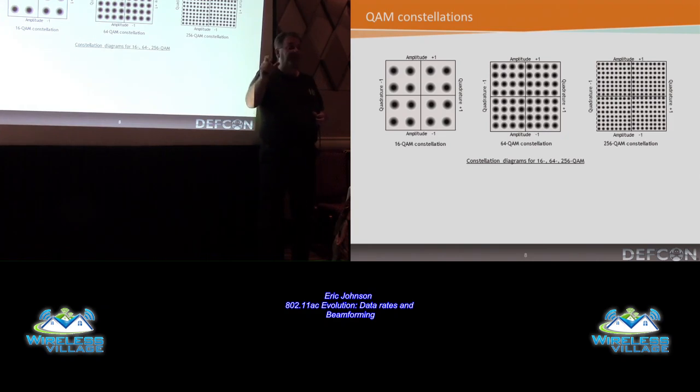Now, there's some fancy mathematical tricks in the transmitter to scramble the bits and to randomize them to make sure that you don't get too many 1s or too many 0s, because that can have some interesting effects sometimes on receivers. So you have an interleaver, so you take your bits that maybe have a bit stream like this. So you take the last bit and the first bit, and it kind of all gets jumbled through a scrambler. Then you interleave, and then you run it through your encoder as well to do the forward error correction. And so there's some rules that come in the mathematics there, but other than that, once the symbols are created, they're just pushed out over the air.